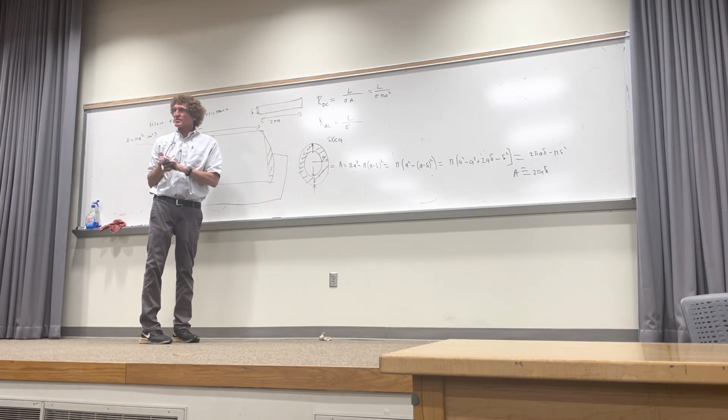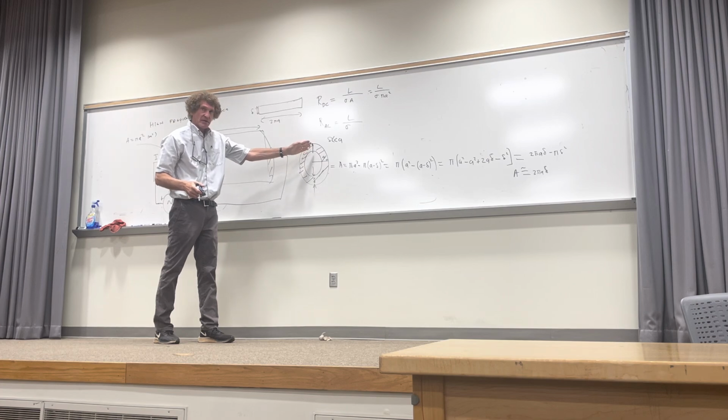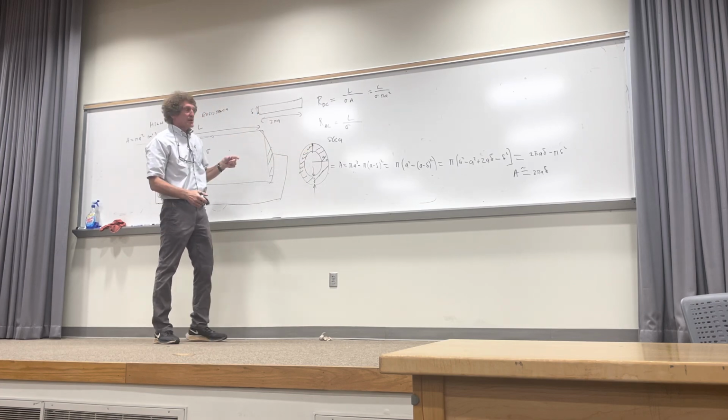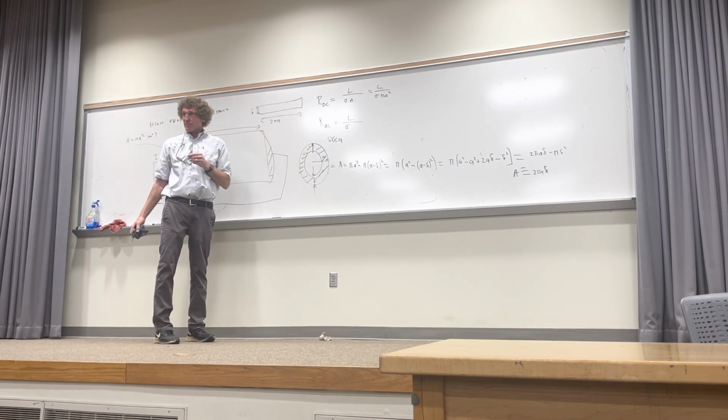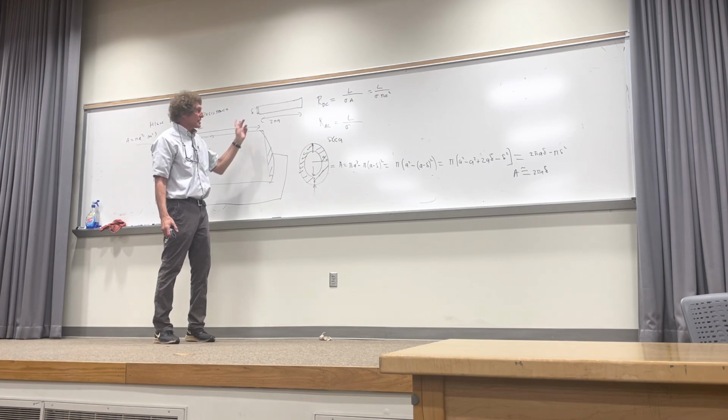Do y'all follow me on this, class? Just take this right here, cut it right there, and then straighten it out. Well, what's the area there? It's 2 pi A times the skin depth. And that's the best way to keep that in the back of your mind, to see it. Just assume everything flows near the surface of the wire, and let the thing go down one skin depth, break it, and spread it out like this.